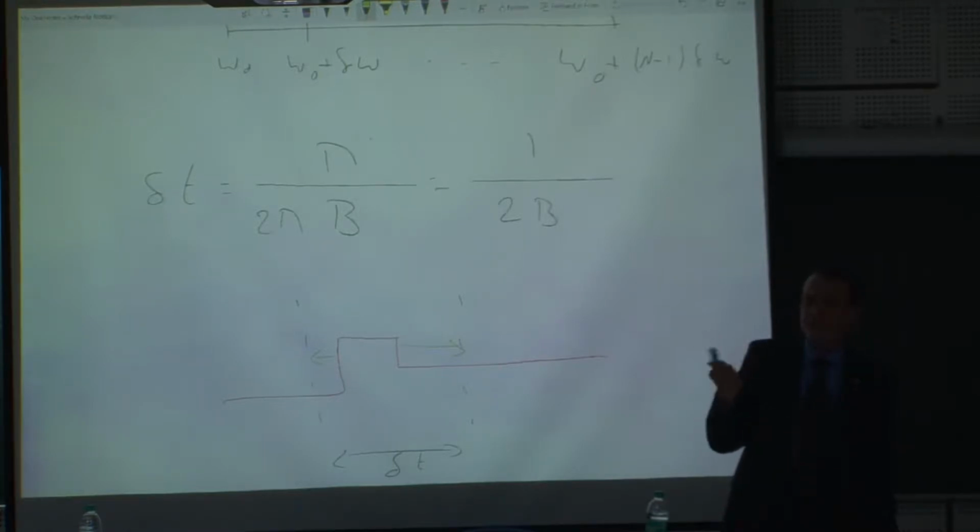So this gives you the feeling of the resolution, and you may raise the resolution. I will discuss resolution on another occasion in terms of convolution and so on. But at least now, because we discretized everything, we work with discrete data. You know now that the higher the bandwidth, the better the resolution. Okay, this is one aspect.